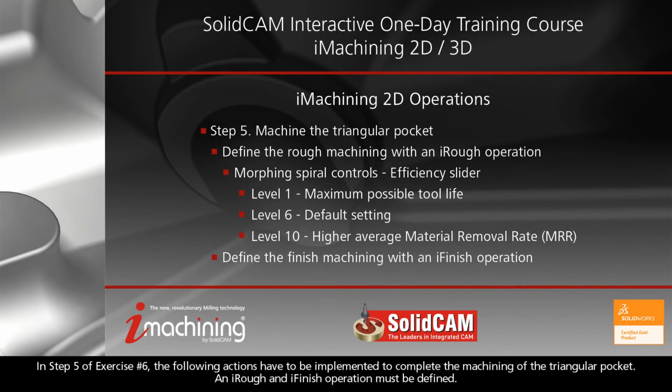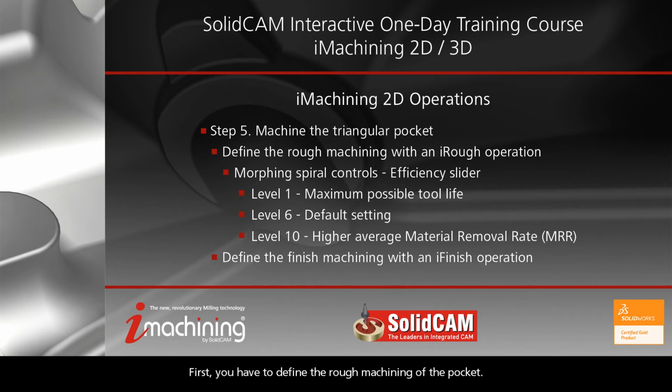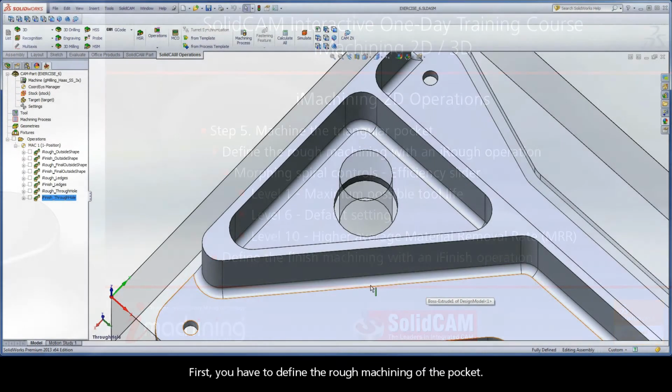In step 5 of exercise number 6, the following actions have to be implemented to complete the machining of the triangular pocket. An iRough and iFinish operation must be defined. During this step, the efficiency slider is used for morphing spiral controls to demonstrate its effect on the iMachining toolpath. First, you have to define the rough machining of the pocket.